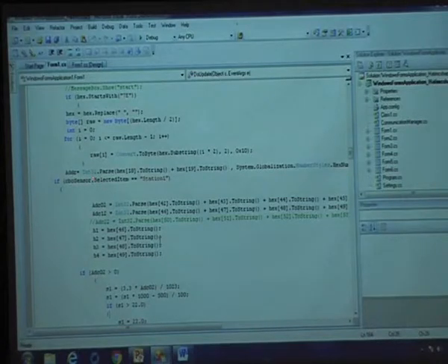So here I have written parse of x of 42, x of 43, x of 44 and x of 45. Look for these hexadecimal values of 42, 43, 44, 45. They correspond to channel pin number 20. Similarly 46, 47, 48, 49 correspond to pin number 19.